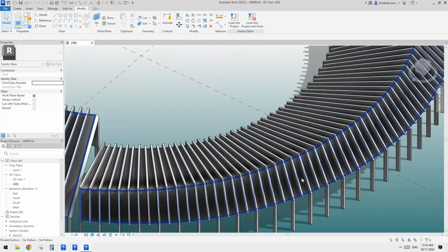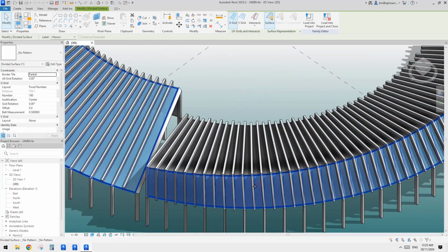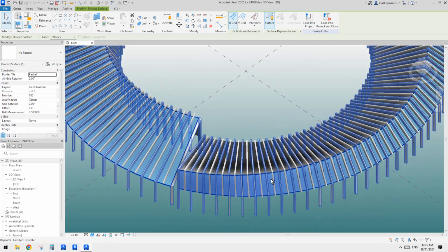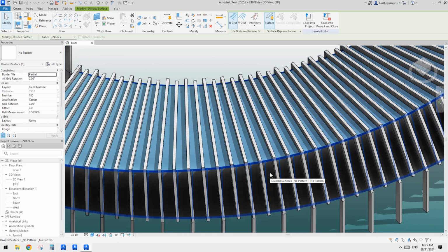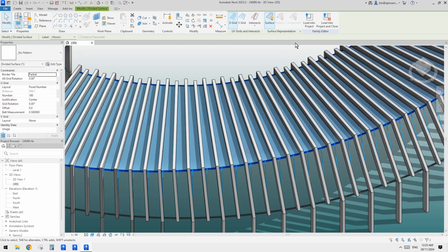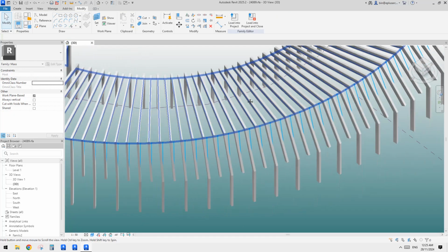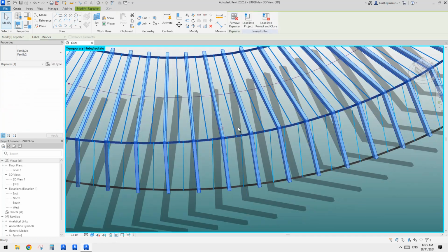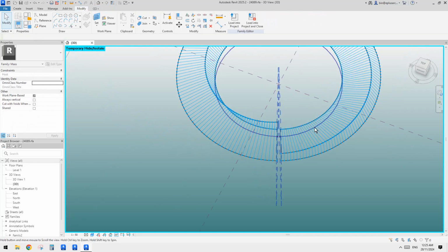So we did this yesterday, but for some reason, see here, this is this and this, they are different divided surfaces. So the pattern, they don't line up. Hang on, let me think. Okay, so maybe I'll just go here, uncheck the origin face surface. Sorry. And yeah, now it's a little bit hard to see. Hang on, where's my grid? Okay, so maybe it's hidden by these. I'll just type HH. Yeah, so this is the reason, because they are not lined up. Okay, so today we try to